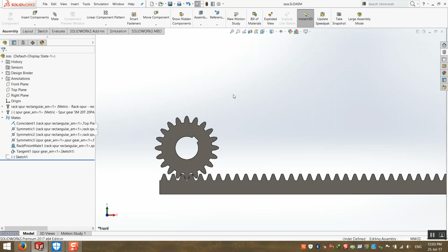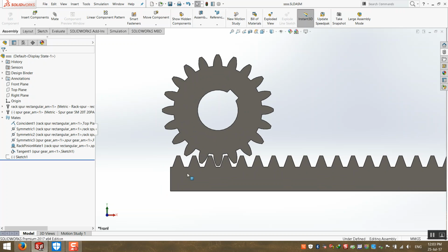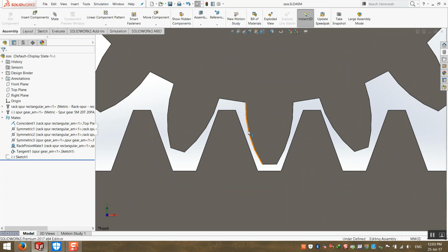The contact diameter, not the outer, not the inner. The contact one here. It's very important. Your design is based on this diameter because that's the main contact point which generates the movement.